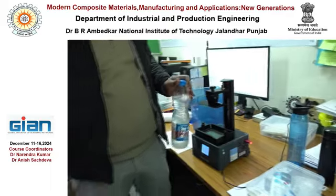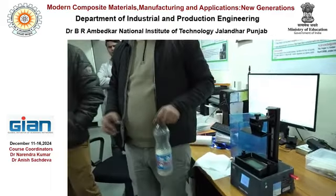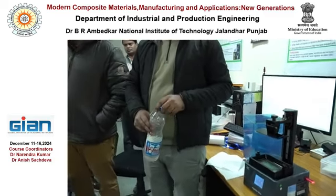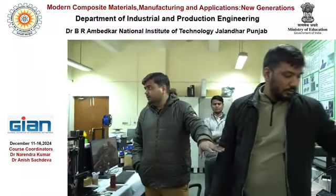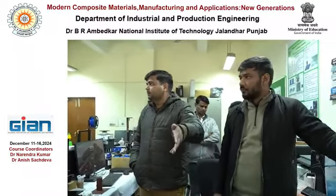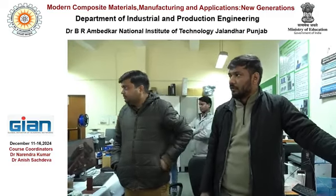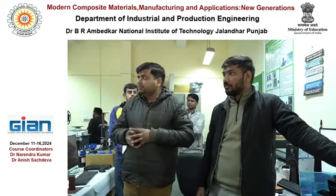That is IPA, isopropyl alcohol is the chemical name. We can wash. Whenever you want to change the material, you can change it, but first you need to wash the tank, right? By using this chemical only. Then you can pour the second material. Otherwise, it will react, right? It may change the property. You have to use gloves also while handling these UV materials.